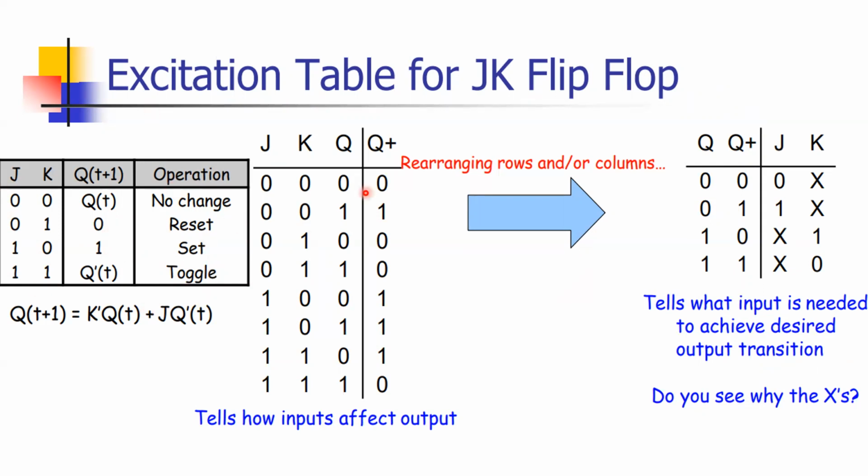Using this truth table, now we are generating the transition table. So in the transition table, first JK is 0, 0, so we are writing here 0, 0. When JK is 0, 0, the previous state is either 0 or 1. So if the JK is 0, 0, whatever be the value of the previous state, that will be your output. So when 0, 0, the previous state is 0, so output is 0. Again 0, 0, the previous state is 1, so output is 1. This is the first line.